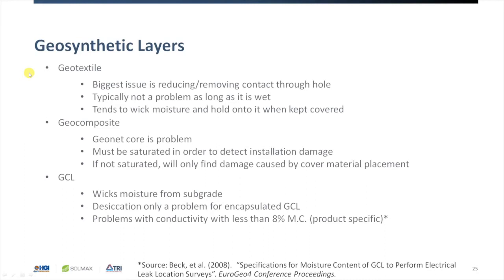So the geocomposite needs to be really wet, especially in order to detect damage caused before the placement of the geocomposite. So if it's not fully saturated, and I would say with standing water, you're only going to be able to find the damage that actually breaks the geocomposite, so the damage caused by cover material placement.